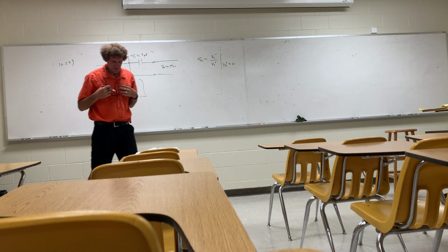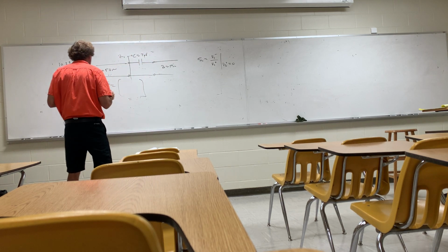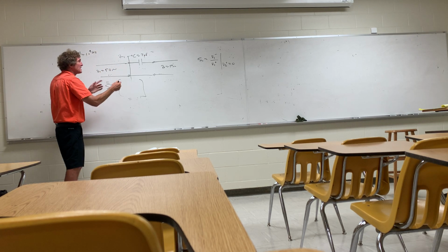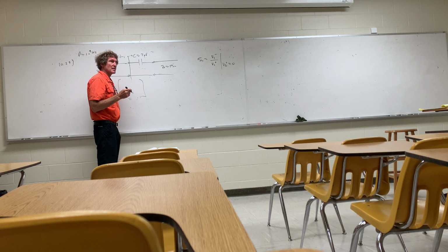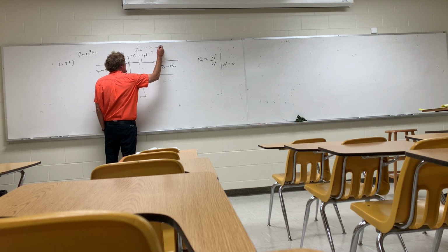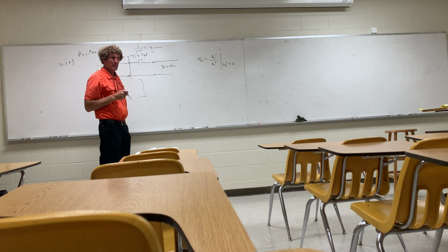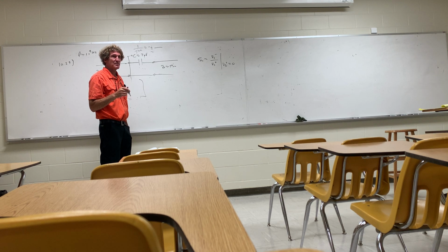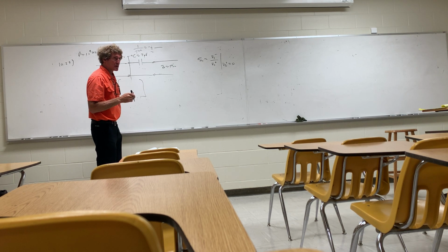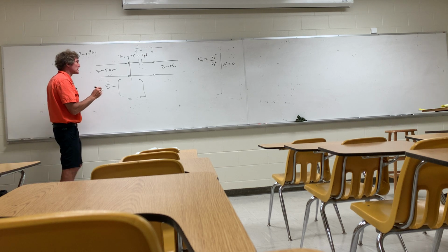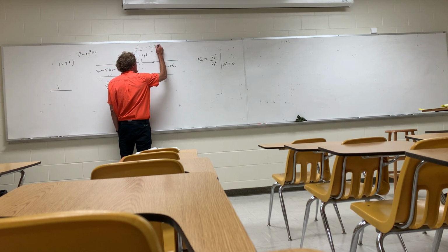So the frequency on this one is 1 gig. I need somebody's help on this one. If we have a frequency of 10 to the 9th hertz, I need really the impedance of that. What is it? 1 over j omega C, right? So 1 over j omega C is minus j and the value: 1 over 2 pi times 10 to the 9th times 2 times 10 to the minus 12. About 100 ohms. What do you get? 79.6. Is that right? I got negative 79.6 j. Yeah. So this is negative 79.6.